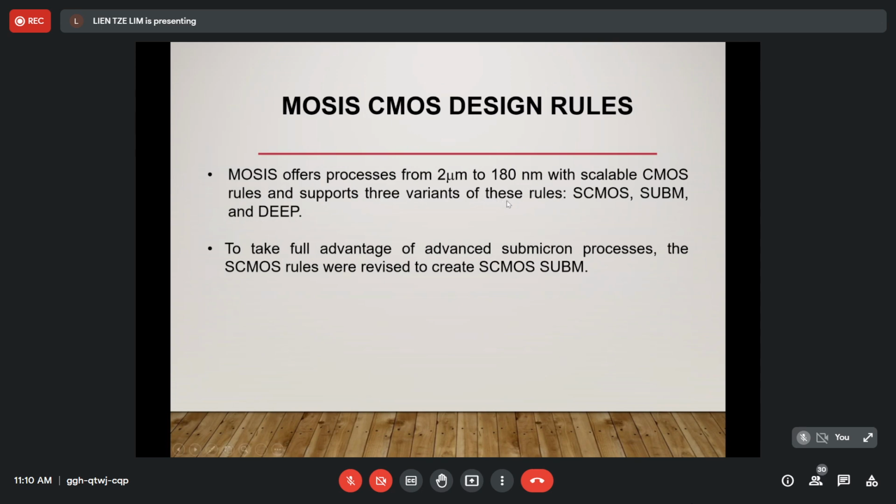The 3 variants of these rules are scalable CMOS, sub-M, which means submicron, and deep. Deep is one of the rules in layout design rules. We call it deep rules. To take advantage of the advanced submicron processes, the scalable CMOS rules were revised to create scalable CMOS submicron.